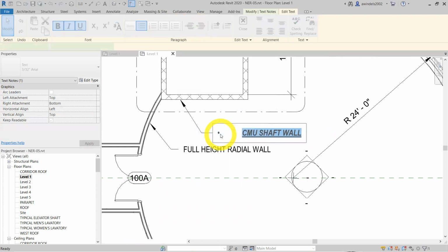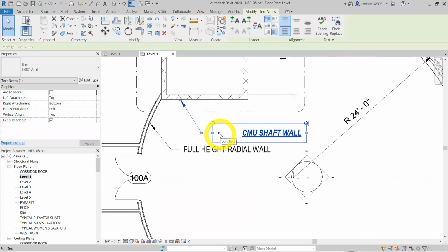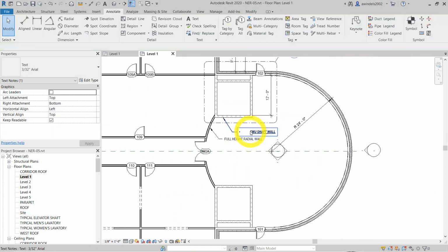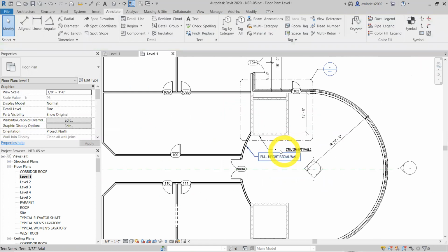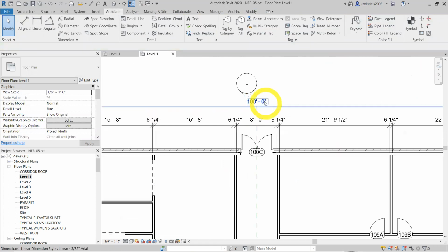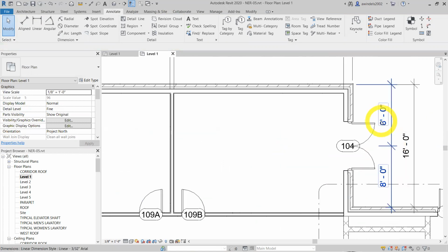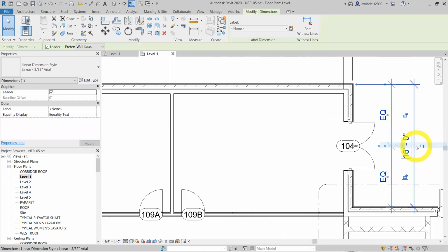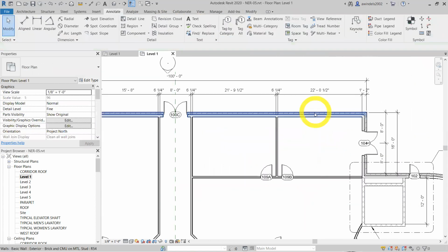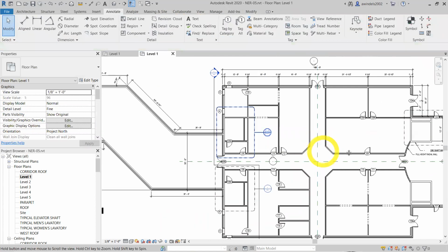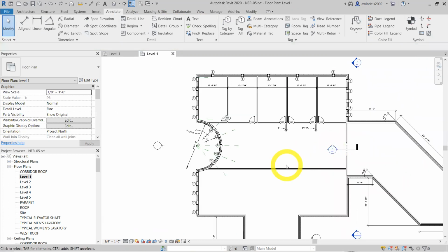So that's the end of that, which pretty much wraps up the chapter. That part's pretty easy compared to the dimensions, but at this point, you're a little handier with dimensions. You know how to use leaders and text a little bit better for annotating. You know how to constrain things a little tighter and equally space things if you want, or constrain them and delete constraints, how to be surgical to do that so they're not still hidden in the background.